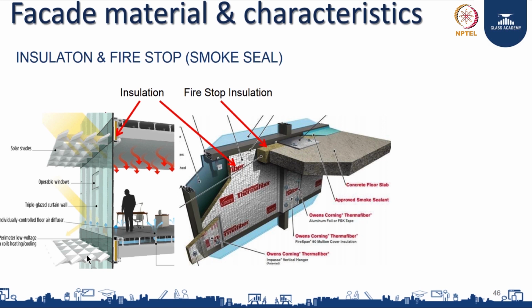If there is a fire, a lot of people get injured first with the smoke. They can't inhale, and then they get disease, and the worst thing happens. So, smoke is the first thing you have to take care of, then fire. So, fire spread and smoke have to be contained within the floor. Hence, the design of fire stop is very crucial between floor to floor or between walls or between adjacent rooms. So, the design has to take care of all those things, and these are the materials available. They have mineral wool, they have rock wool. They are all made of non-combustible material.